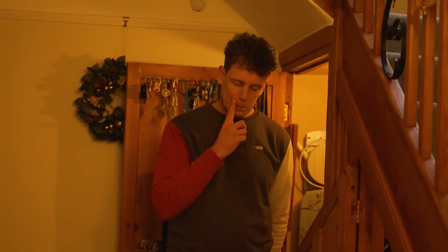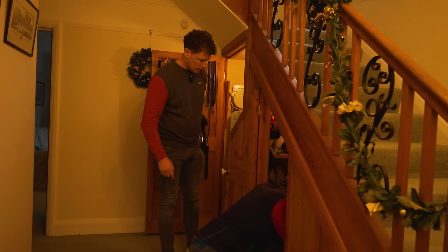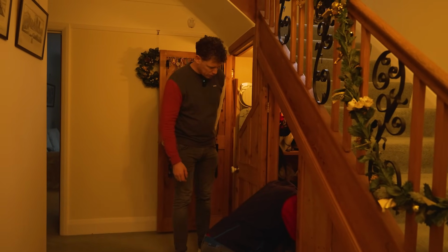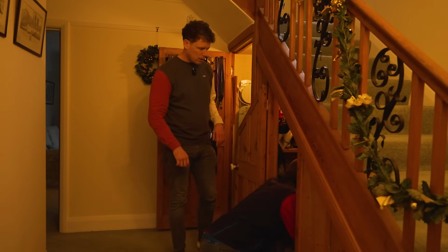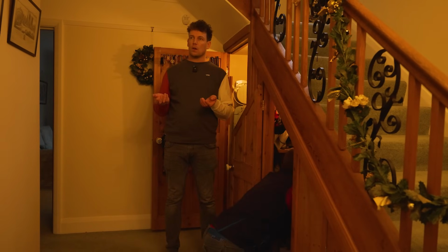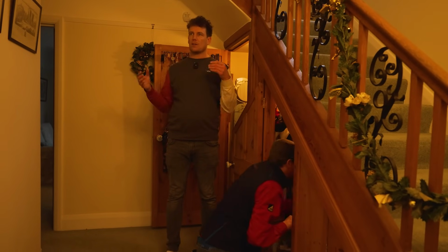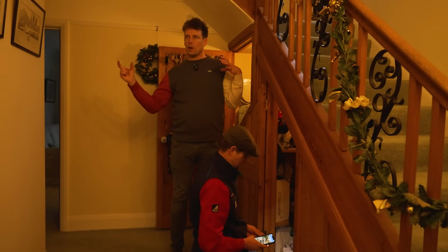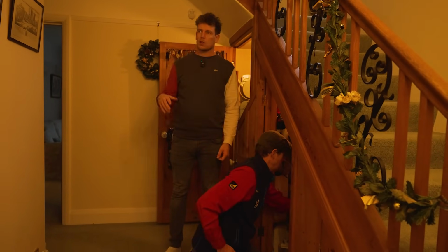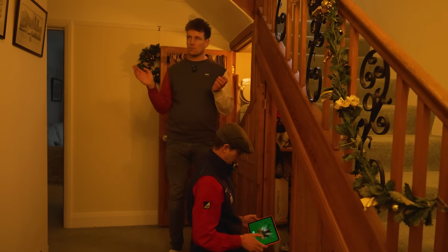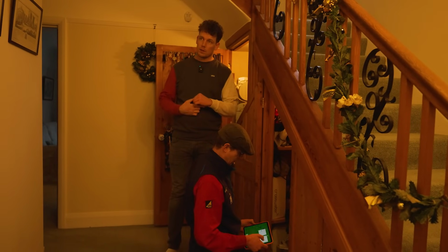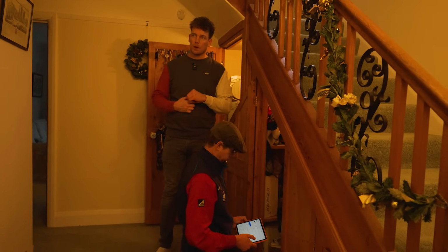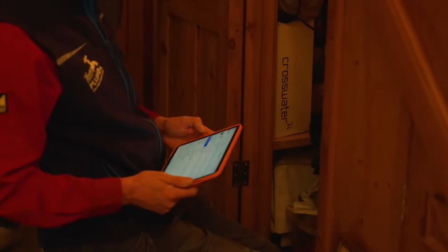You don't have a car charger at the moment, but you might have one in the future, right? They'll have to do the same thing when they come and do a fuse upgrade, whoever puts in a car charger. They'll have to do a maximum demand calculation because they'll have to add what you're using at the moment to the new load. Car chargers take much more energy than anything, much more than a heat pump. It's 7 kilowatts, whereas a 12 kilowatt heat pump, which is probably what we'll install here, will take about 5.